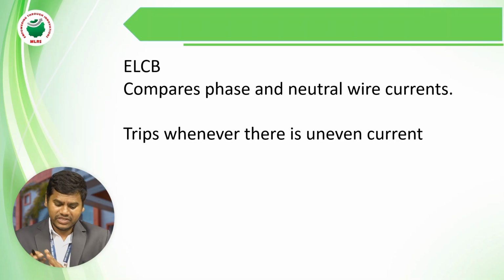It compares phase and neutral wire currents, and it trips whenever there is uneven current.